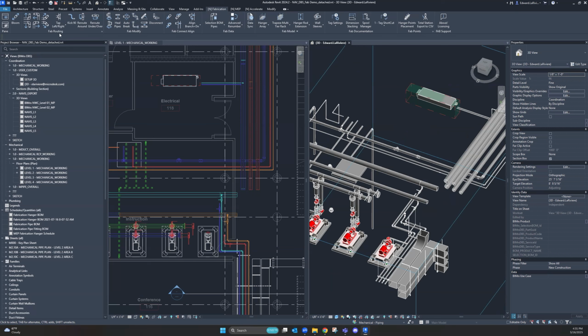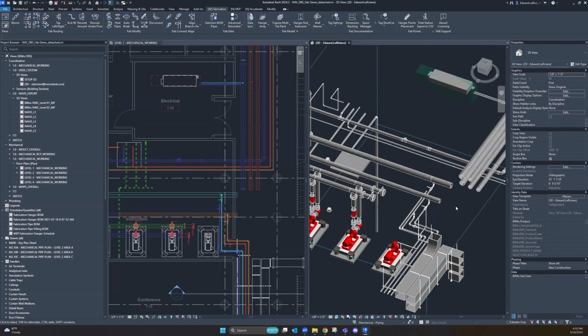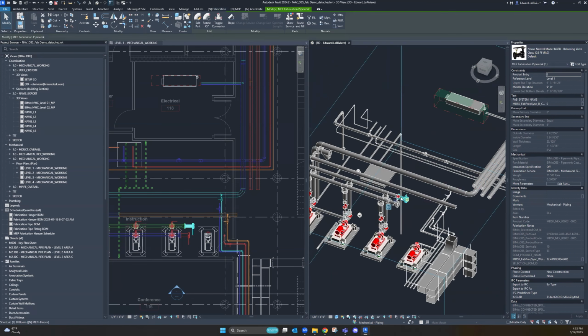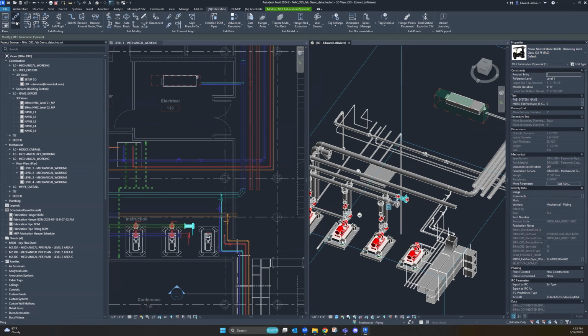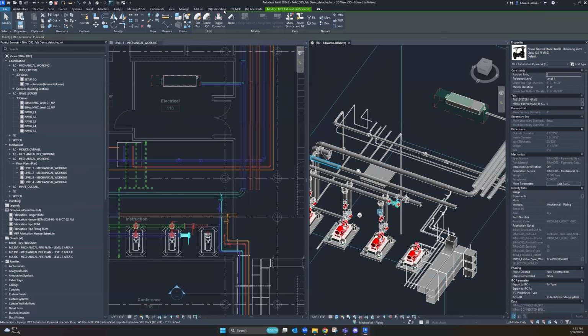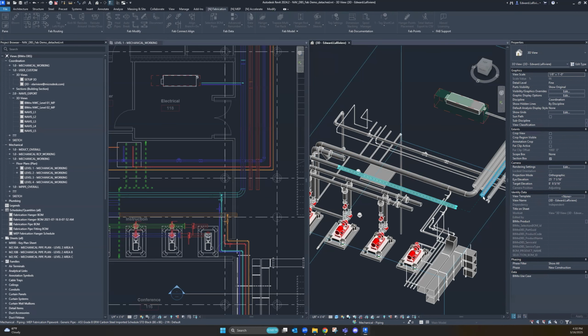As we take a look up inside Fab Routing, we'll find there's a pretty nice update for Reroute Under Over, Reroute Around, and Kick 90. These three tools let us do some of those commands or routes we've done in the past a little bit easier. So anyone using Naviate may remember the standard little connection we do over here, allowing us to go to each of those elements, bloom them out, work with those spaces, and connect these things together a little bit easier. Some of those were very easy, doing those trim to corners for the elements that are at the right height, but that second height is where it gets a little bit annoying.